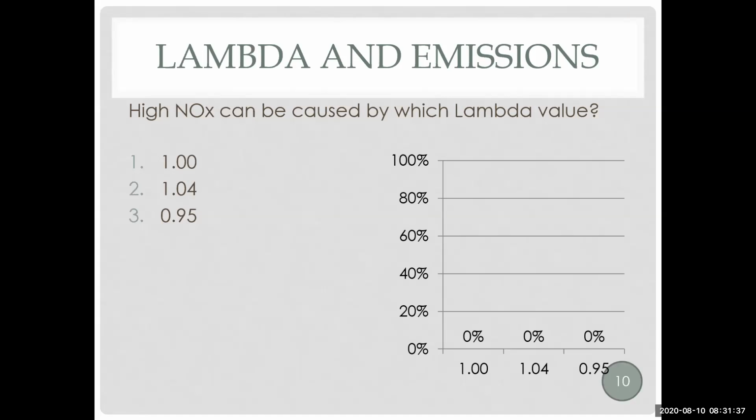NOx means heat, and a lean mixture runs hotter. Anyone who has worked with little 2-stroke engines or motorcycles knows that with a lean mixture, you'll melt the piston down. The reason for that is excessive heat. About the smoke check, does the NOx show on a normal engine? Yeah, we normally will see some NOx.